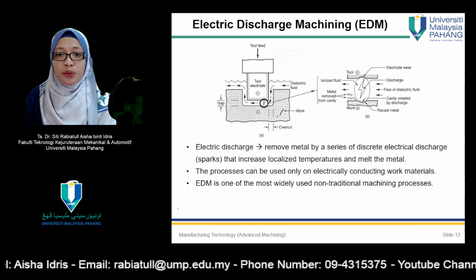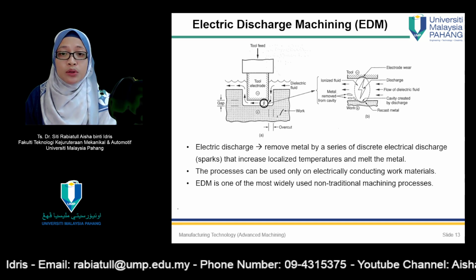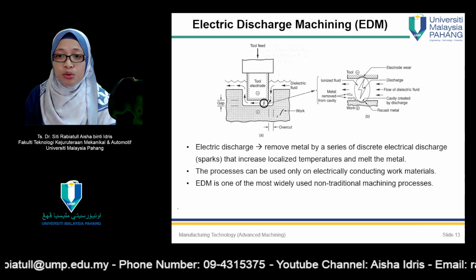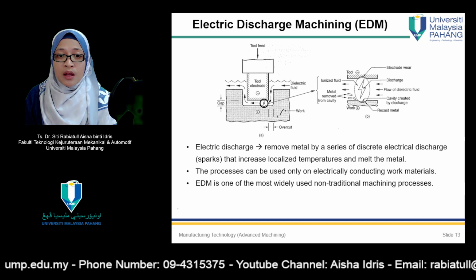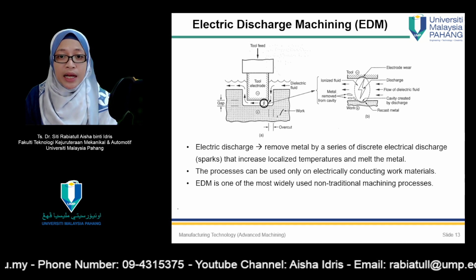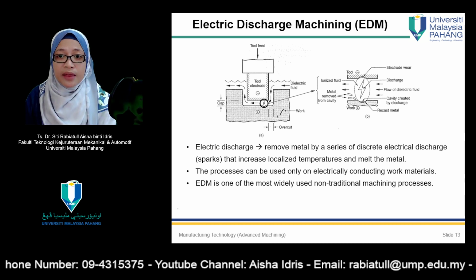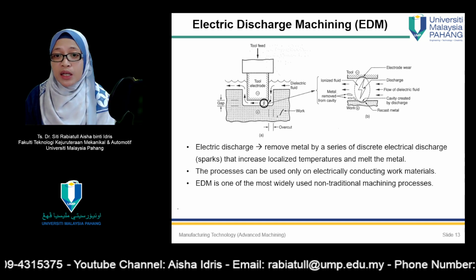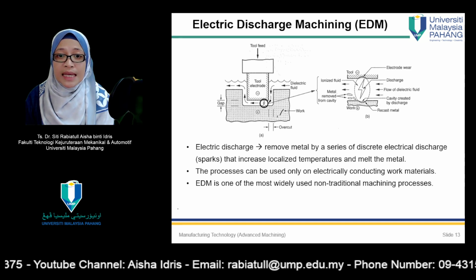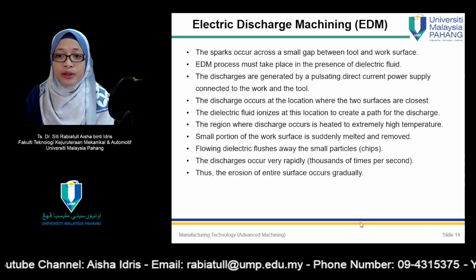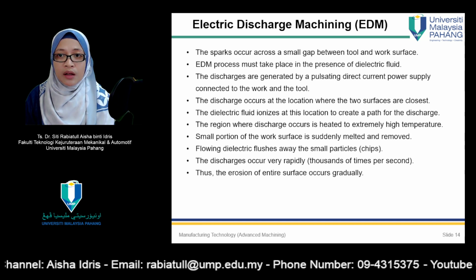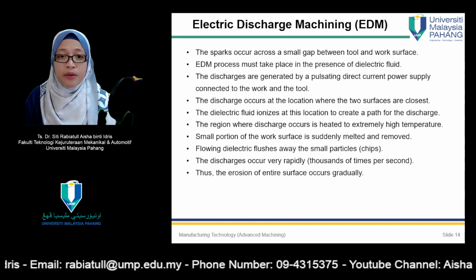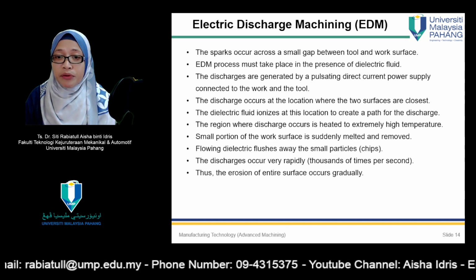Whereas figure B shows a close view of the gap between the tool and the work. The discharge occurs at the location where the two surfaces are closest. The dielectric fluid ionizes at this location to create a path for the discharge. The region in which a discharge occurs is heated at extremely high temperature, so that a small portion of the work surface is suddenly melted and removed.